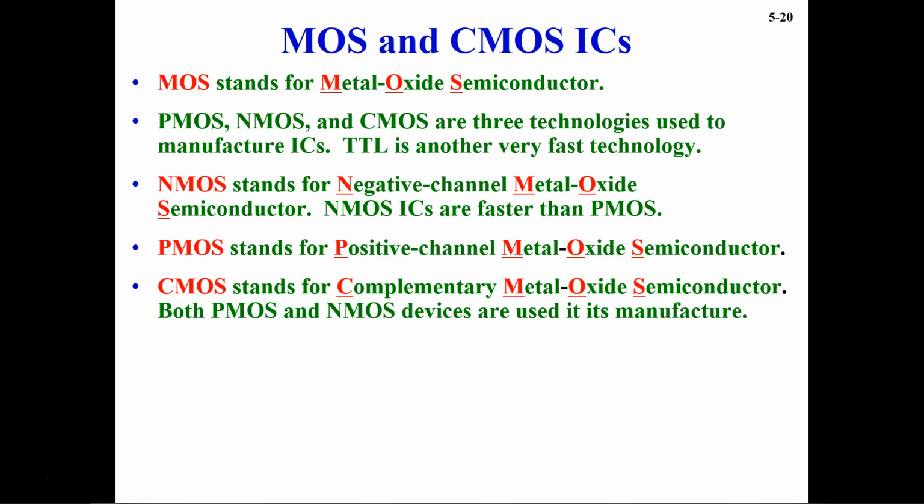If you remember, in previous slides we discussed that the fan out for the CMOS 4000 series was about 50, which was huge compared to the standard TTL, which was 10. They also have a good noise margin, and some low voltage CMOS can supply as low as 1.7 volts. That's really small voltage, which means the IC is also going to be very small.